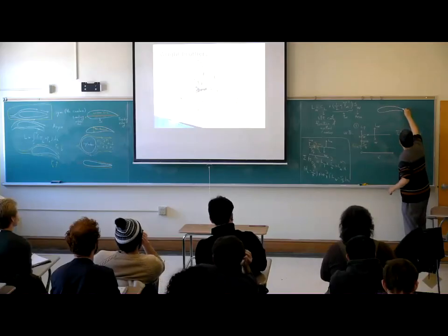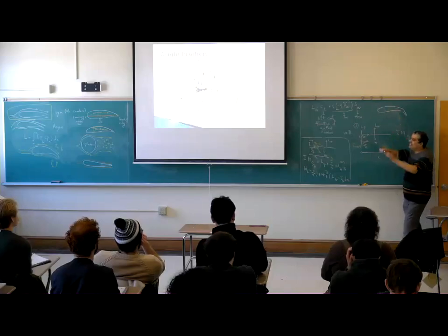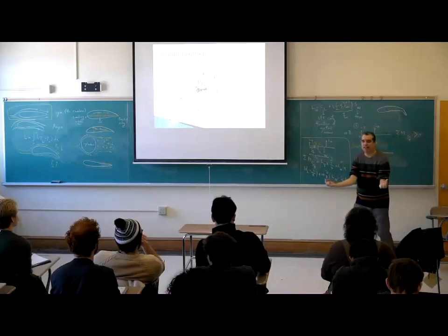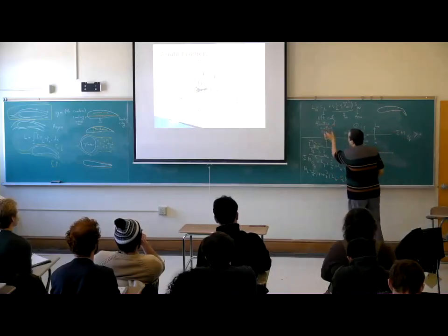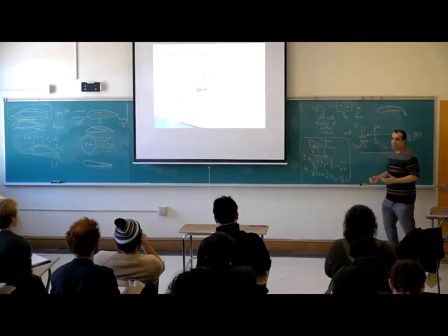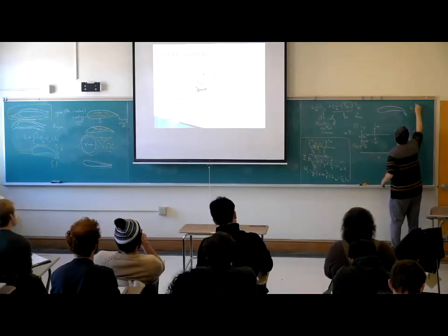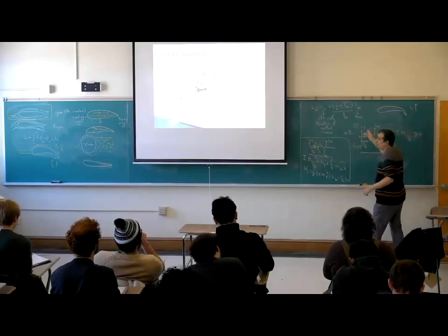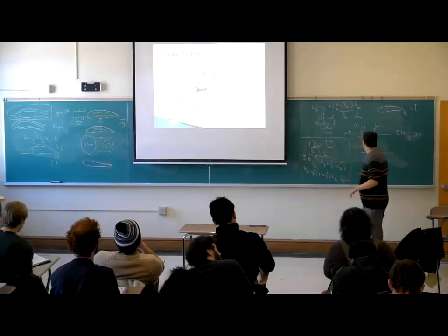They move this region more down. It increases the curvature of the airfoil, and I told you lift coefficient is a function of airfoil camber. Camber is curvature. So lift goes up. This is for banking this way, with my right wing.